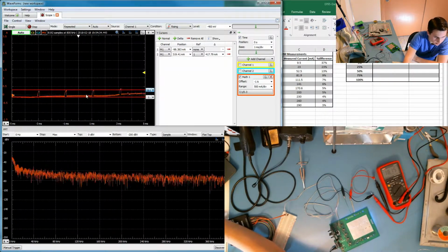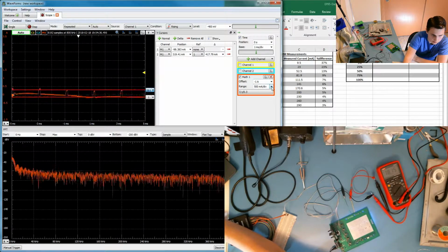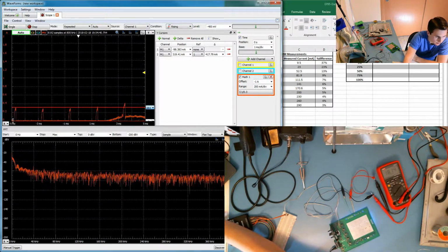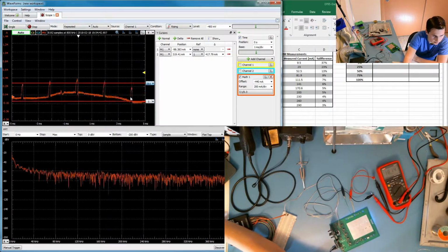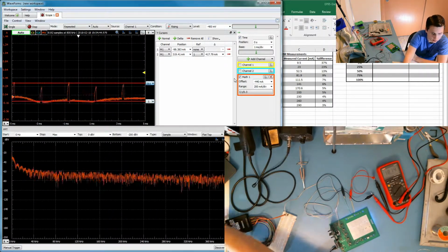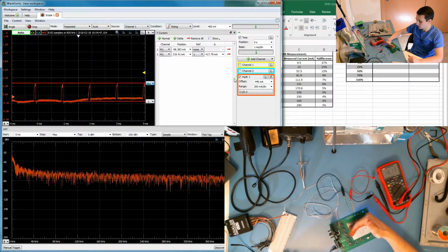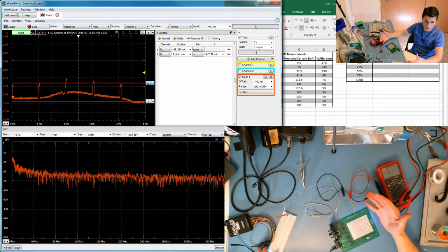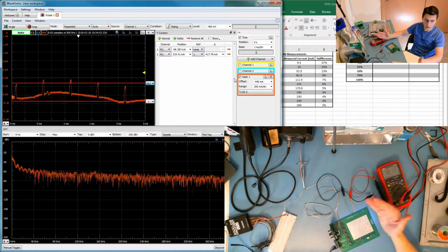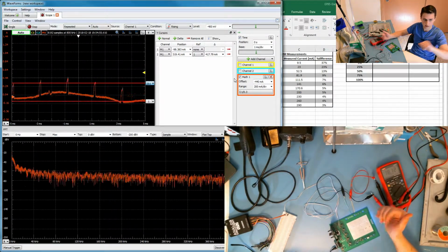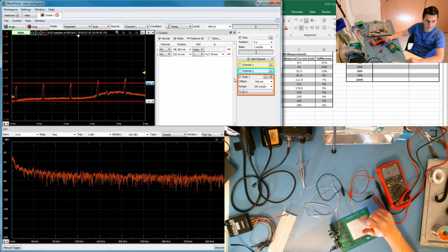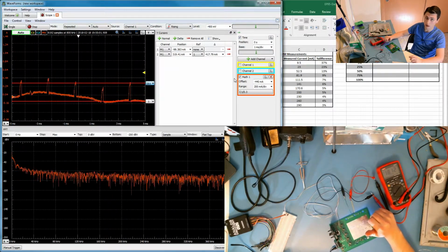So it looks like what we're seeing here is that the way this IC is controlling the current is by giving it peaks of the maximum 333 milliamp current, and then just pulse width modulating that to achieve our total brightness, which is not what I expected at all.